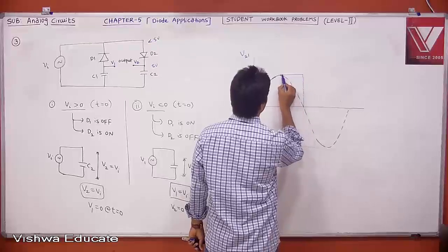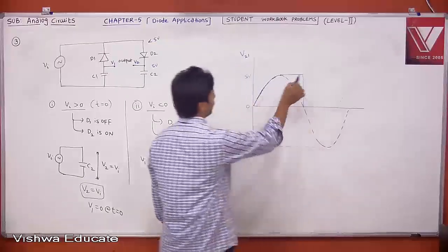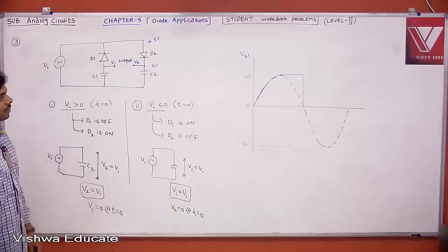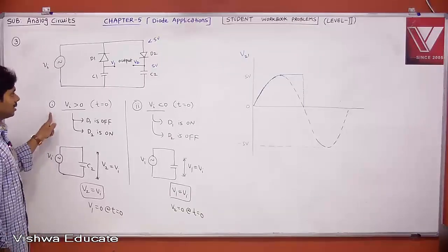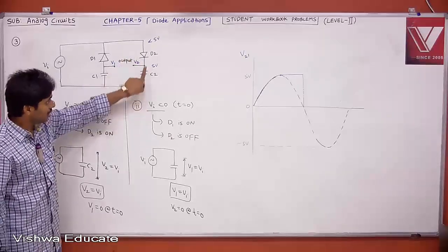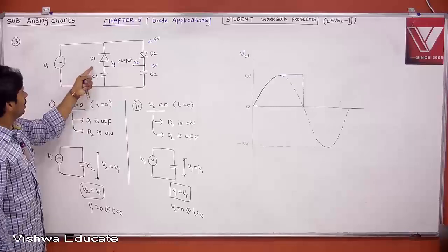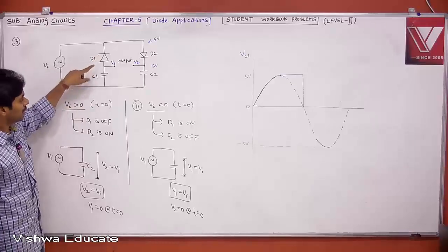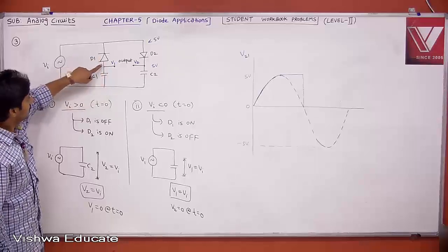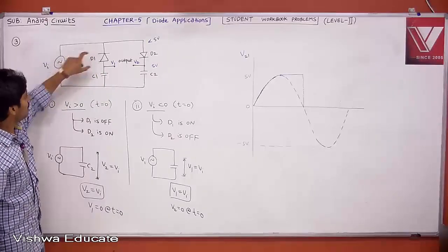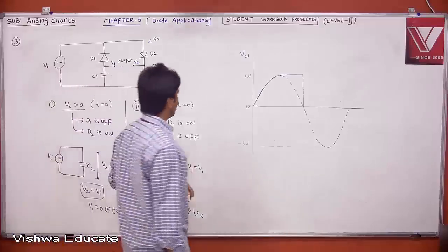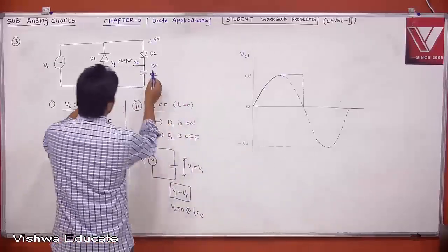I am speaking with respect to the first cycle. Now, when VA is negative, then already your capacitor V2 is charged to 5 now. Now when VA is negative, this is what is conducting. Let us say initially this is 0 because we are in the starting cycle. Then when this is 0 and this is negative, therefore this is on, then your capacitor C1 is tracking to negative voltage, but your V2 is still 5.